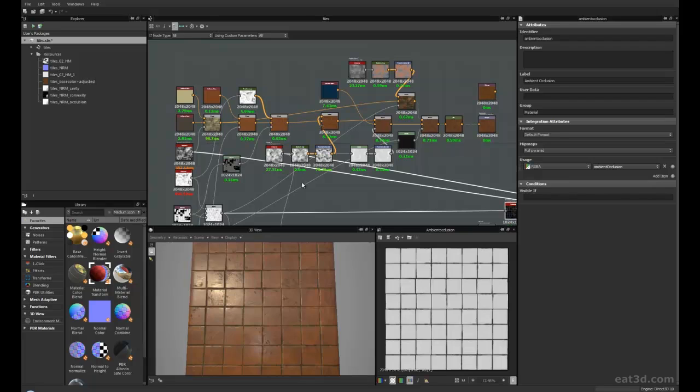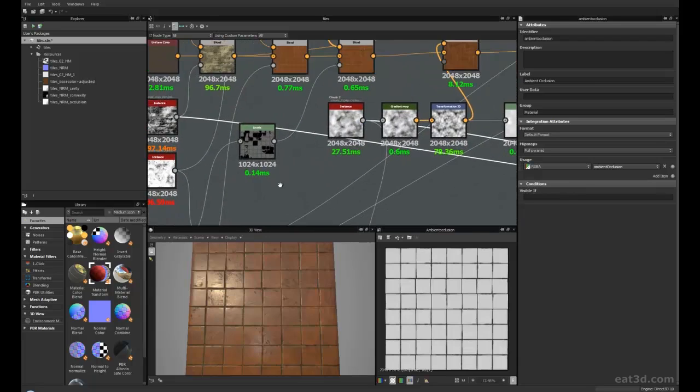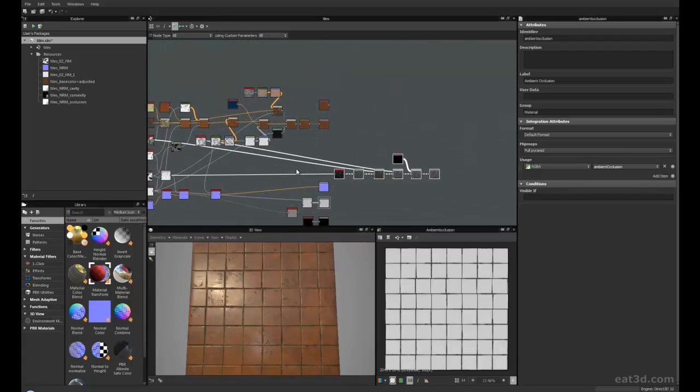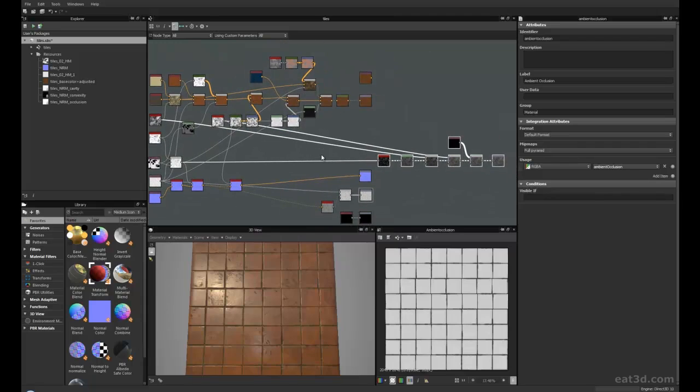So, as you'll see as I go through these nodes, there are no photo references anymore, which is great, because when you're making a physically based rendering texture, there are a few key things you need to remember. The one key thing is in the albedo map, which used to be the diffuse and is now called albedo. The reason I call it albedo is because it doesn't want any shadows in it, doesn't want any cavity. Well, you can have very small cavity information in there, but you don't want ambient occlusion in it at all. It wants to be completely stripped, and that's why using photographic imagery can be difficult.